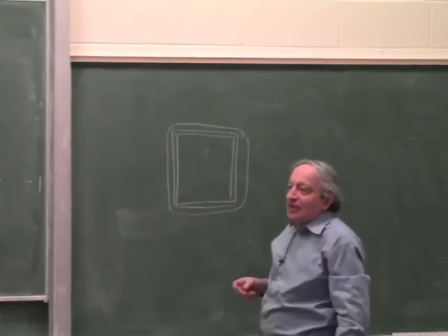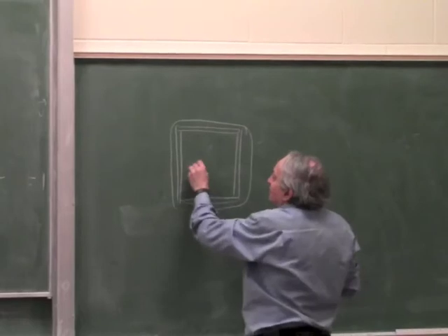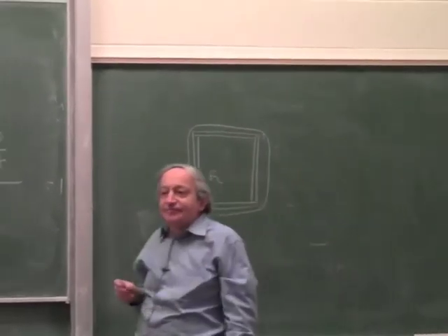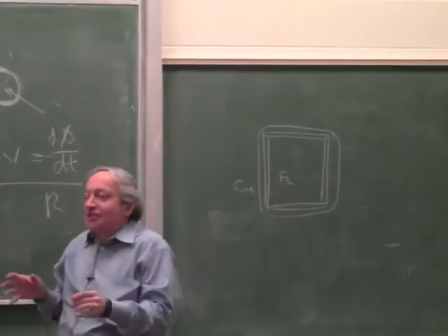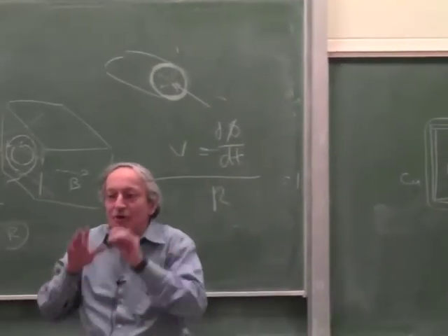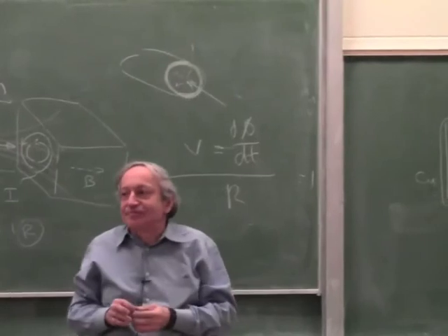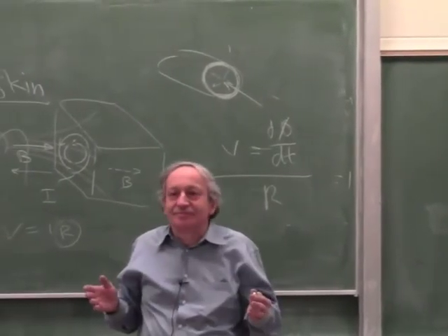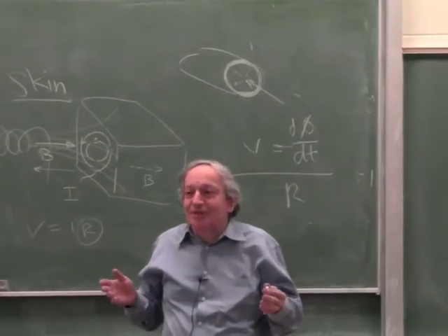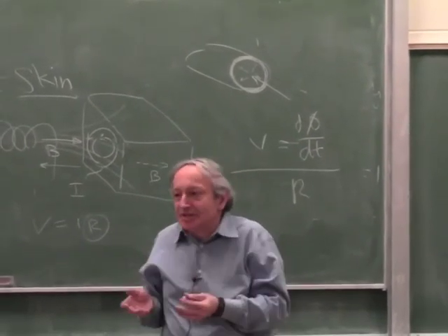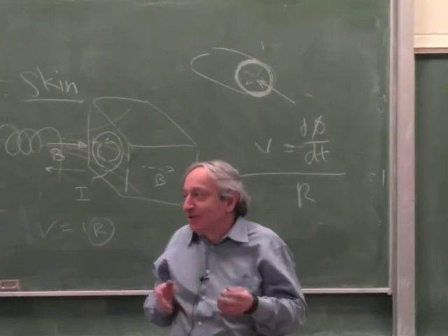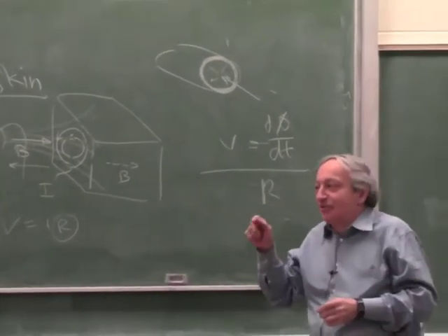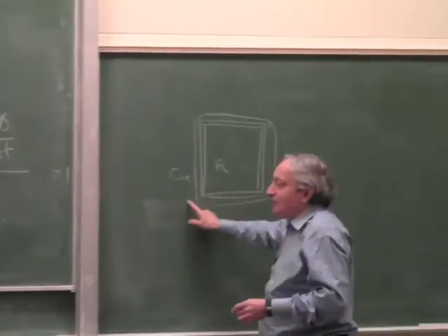Now, what is better, to put the steel inside and copper outside, or the other way? If you look at these boxes in instruments, it's always copper outside. Why? Very simple, nothing to do with shielding. Steel rusts, copper doesn't. So it's better to put the copper outside so it's protected from rust. Also it's easier to solder to. When you want to ground it, it's easier to solder to it.